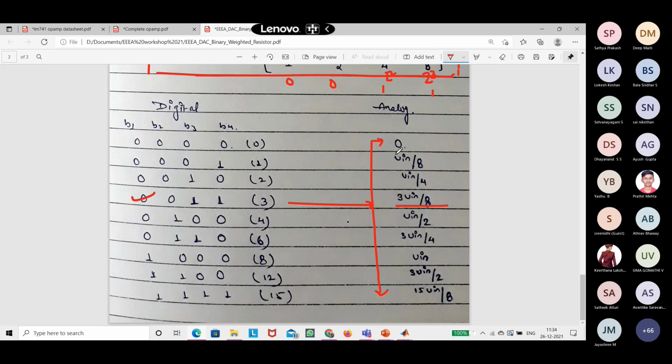In this form, you could get analog values. Analog is basically continuous, but when we are converting from digital to analog, we have these samplings. To increase the level, say for 0 to 5 volts, I have to increase the number of bits. So instead of 4-bit, we go for 5-bit, 6-bit, so that we could increase the number of levels. Okay, that's about the explanation part.